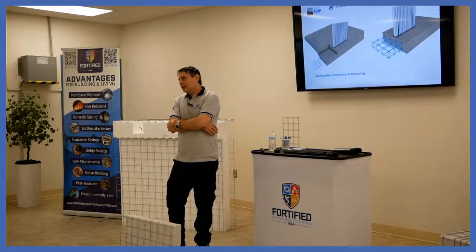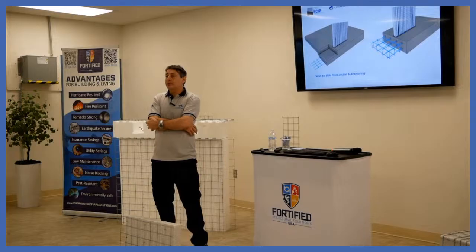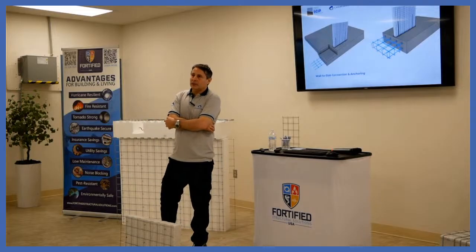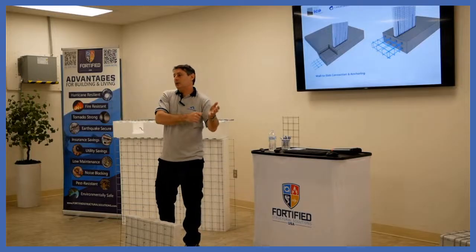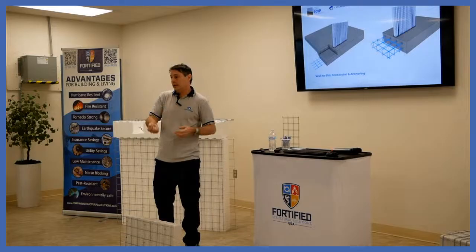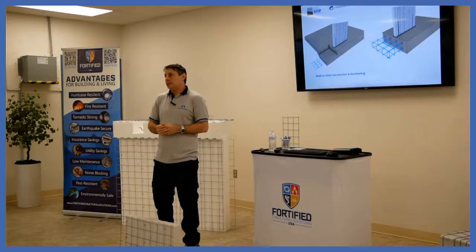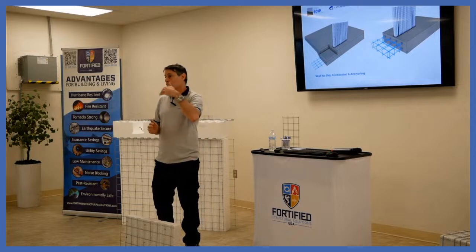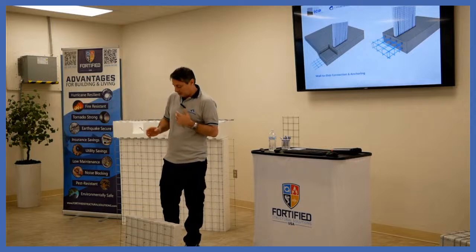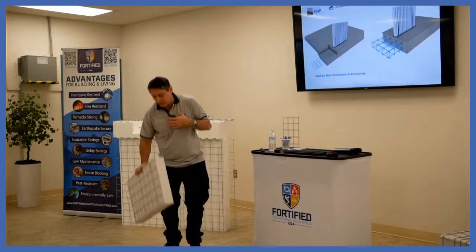Well, basically the pre-design, the pre-calculation of that, is about 10% of the span, just for the height, and then you calculate the rebars that you will need. In the meantime, there's another thing to contemplate, whether you integrate it fully. When I'm speaking about the 10%, it depends.